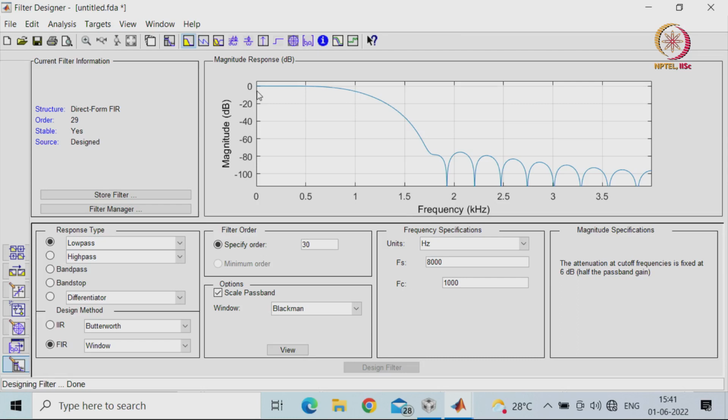which is equivalent to 0.707 of the magnitude. You have to be careful when designing your filter, as the output amplitude may be modified; you will get a scaled version. If you want 0 dB, the frequency I can pass, as you can see, is only up to 500 hertz. If you go beyond it, you will have attenuation in the magnitude, so you may have to compensate.